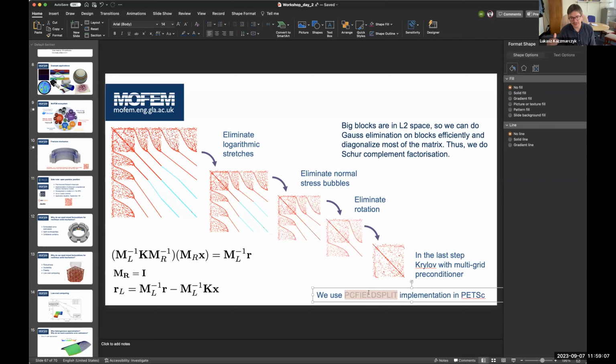We have a whole infrastructure made with PETSc, and then in MoFEM we calculate a Schur complement, and then PETSc exploits that Schur complement, and on that Schur complement through PETSc we can deploy algebraic multigrid, for example, or a block Jacobi solver. So then we can get the scalability from that.